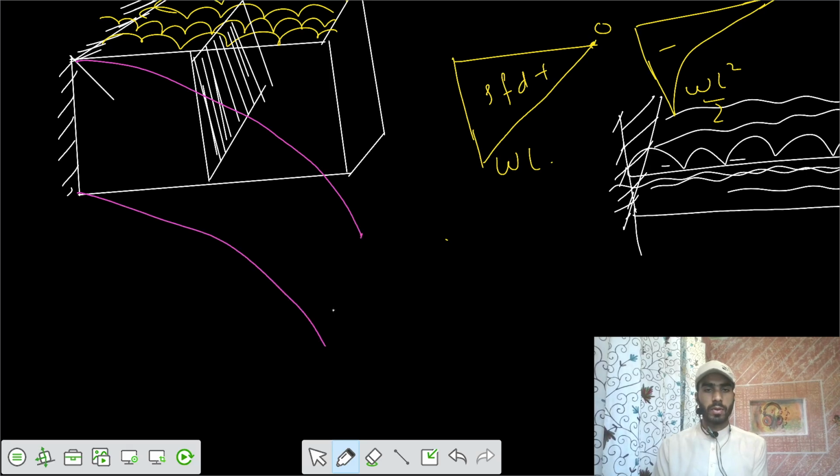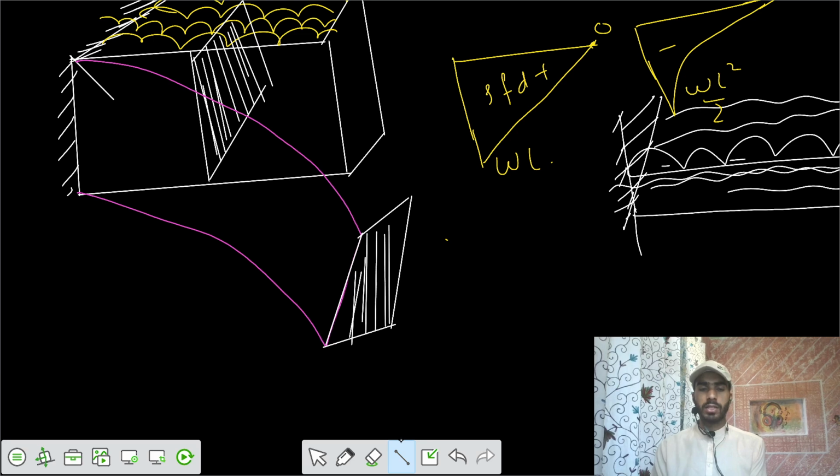Let's say this is the profile after the bending. We say that the shear force is 0 here. That means this one would be without deformation, without change in the angle between the axes. So this is our first plane that has remained plane.